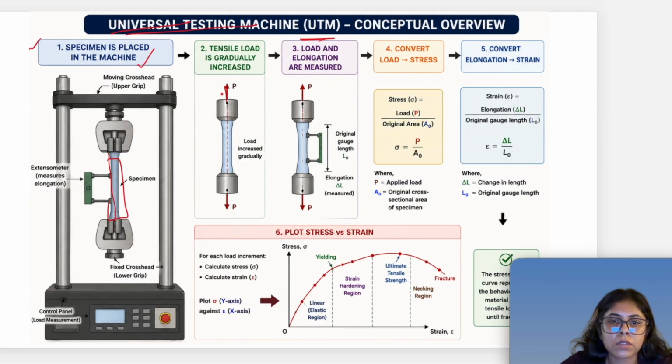So the specimen will be pulled from both the sides. And we will be noting down how much force we are going to apply, and we'll have the original area. Then we'll be just noting down the force which we are applying. After some time, due to this force, this material will stretch, right, and the cross sectional area will reduce, right? So due to the force, the stretch will be there, this is the original length, and then we will be having elongation also.